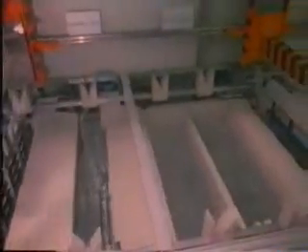In the plating process, the strips are loaded onto carriers and dipped in a series of chemical and water wash baths. In the plating baths, with anodes of tin and lead, the leads are plated with a layer of solder so that the chips can be easily attached to a printed circuit board.